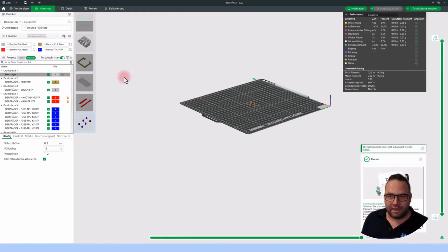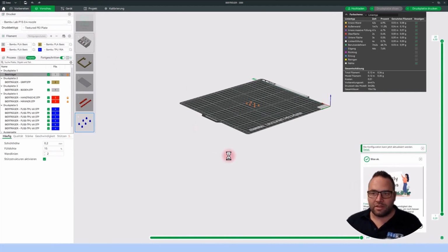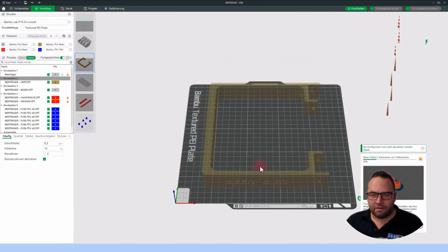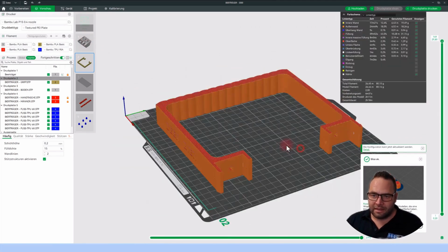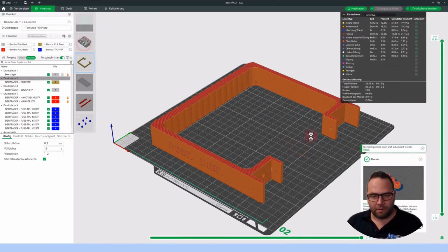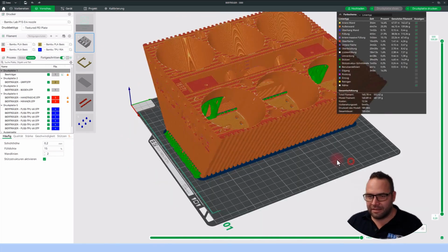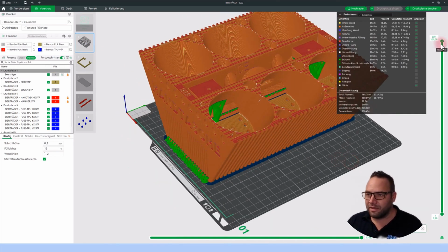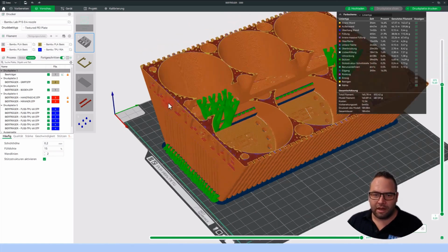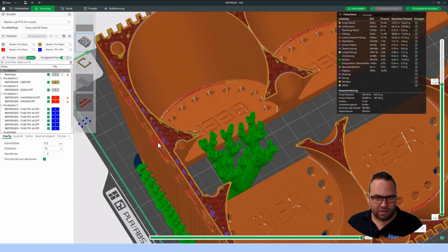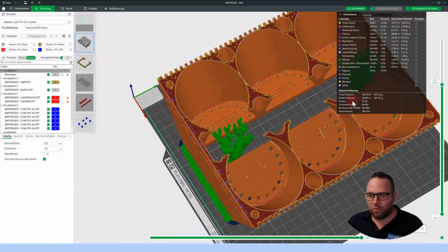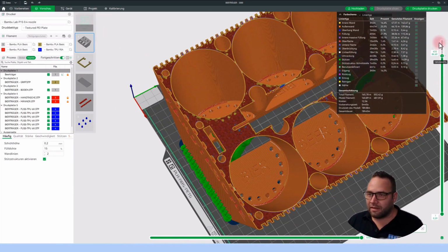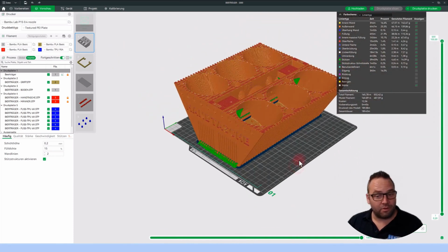You can see that when I click here, I can view the various printing methods and areas of my parts, and it will essentially show me here, for example, also sliced, meaning generated machine code for my printer. Here in the slicer, I can also view my other parts, which means that in this case, for example, I see this engine block would take 18 hours to print. And of course, I can then go down in this area and take a closer look at my parts, such as how my infill is, what support structures I have, and also check whether the print would be successful.